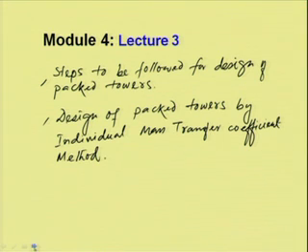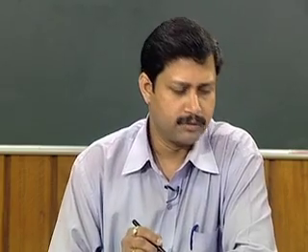In this lecture, we will discuss packed tower design by overall mass transfer coefficient methods and also by height of transfer unit methods. So, let us consider packed tower design based on overall mass transfer coefficient method.